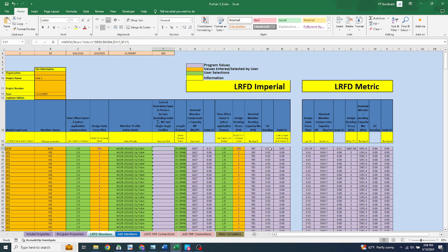So there you go. For a 10-foot length, we have our allowable, or the allowable would be ASD, but the factored figure of 2,627 pounds is what would be there. Now, of course, if we change the length, and let's say we reduced it to 5 feet, then you can see that the factored figures for compression and for bending stress have all increased.